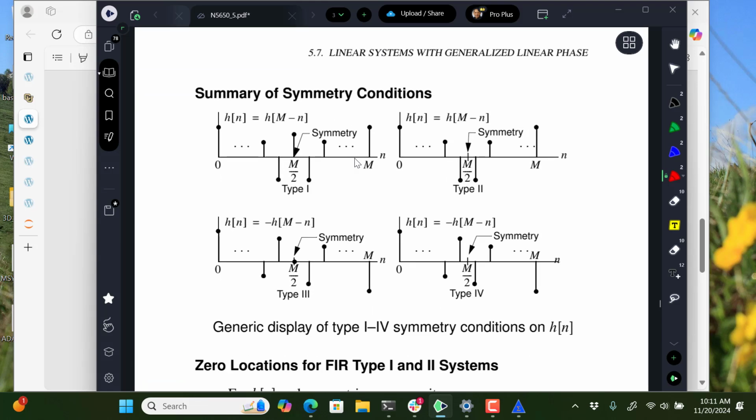I think as a user, I look at certain properties, and this is what I look at if I'm given a set of coefficients. If somebody says we want to model our system, maybe it's from an FPGA, maybe it's code running on an ARM core or something. Where are your coefficients at? They're in a header file if it's in an ARM core, and it's going to be in a coef file that Xilinx likes to use for coefficients because they've got synthesis tools. But I look at those coefficients, and if they're hex, I'll get them into fixed point integers. Whatever. Still, I'm looking for symmetry.